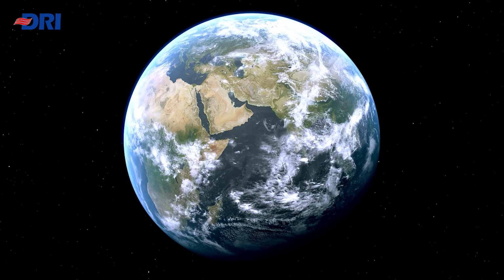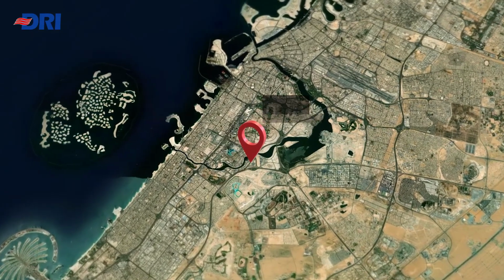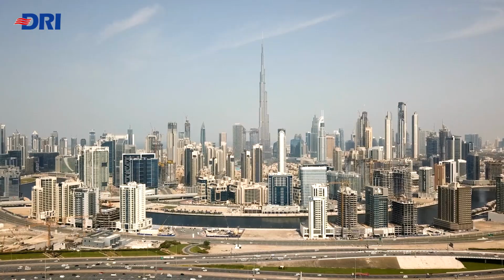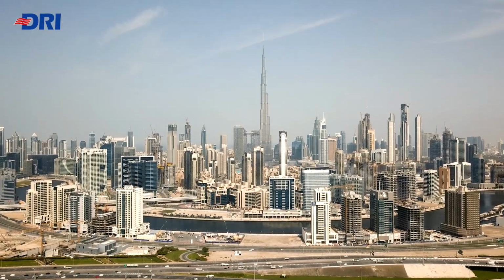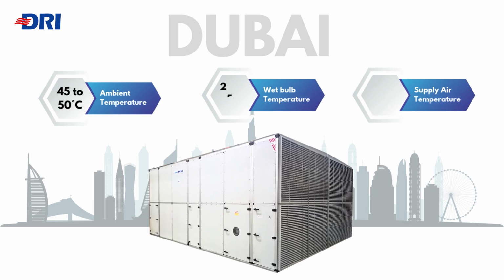Now, consider a different climate like Dubai, which experiences both high temperatures and elevated humidity levels. During peak summer, outdoor temperatures can reach 45 to 50 degrees Celsius, with a max wet bulb temperature of around 25 to 30 degrees Celsius. Despite these challenging conditions, an IDEC system can still provide efficient cooling, reducing supply air temperatures to approximately 22 to 24 degrees Celsius. This represents a significant energy-saving alternative to traditional air conditioning systems while maintaining indoor comfort, even in humid climates.